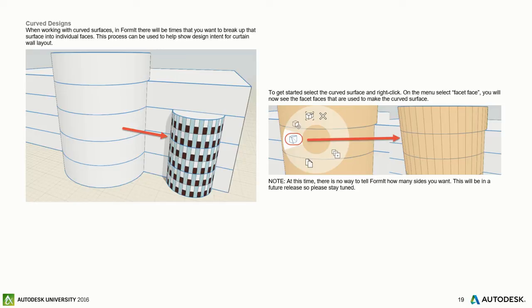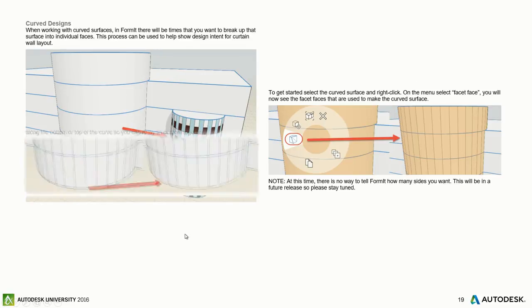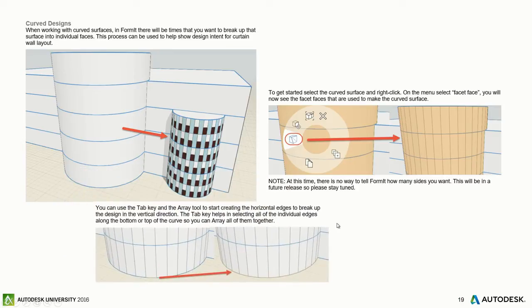So that'll be coming. But even with that said, that doesn't mean I can't grab the lines and manipulate and change. It would just be nice if I had the extra properties and it would speed up the process. And then once that breaks down, I can use my magic tab key to grab those edges, and then I can array that up to convey the vertical breakup of it. Okay? And remember, these blue lines are dealing with levels. That's what's going on with that. So don't just understand this. I have a building. I'm trying to figure out square footage with it.